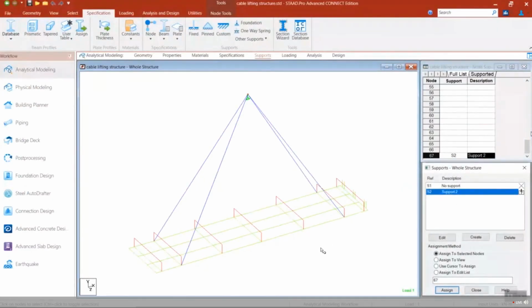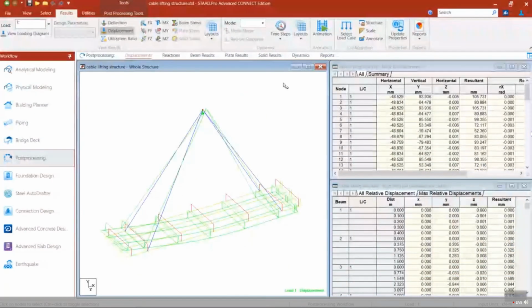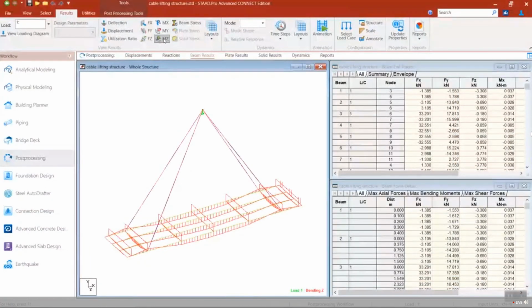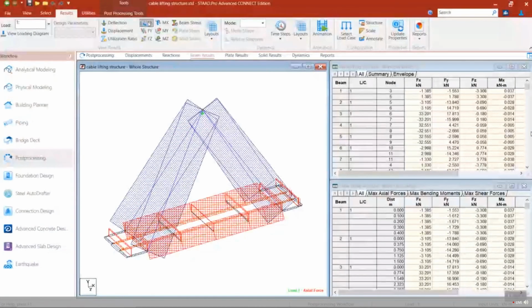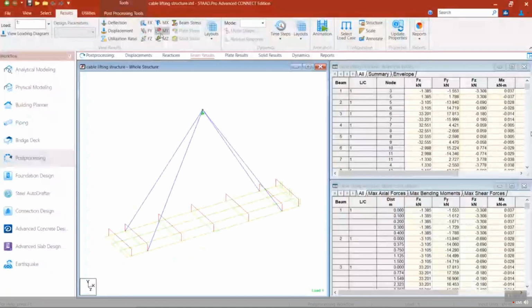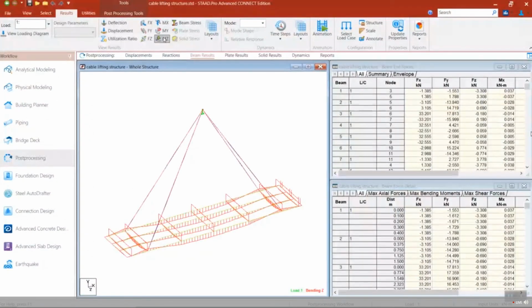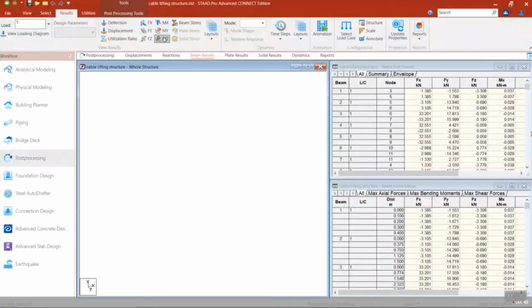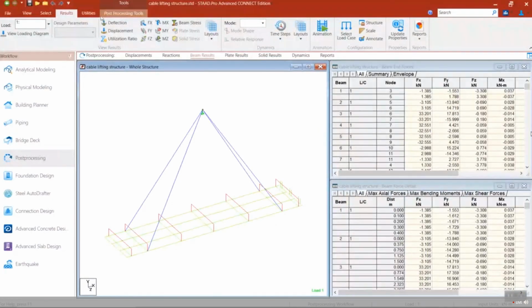Okay, here's a support. You can see I released all except Fy. It's a fixed but support command. And the deflection we already checked. And here's the bending moment diagram. So we need to design this platform for even this lifting load also. And here's the axial force on the cables, all showing in blue color, meaning tension.